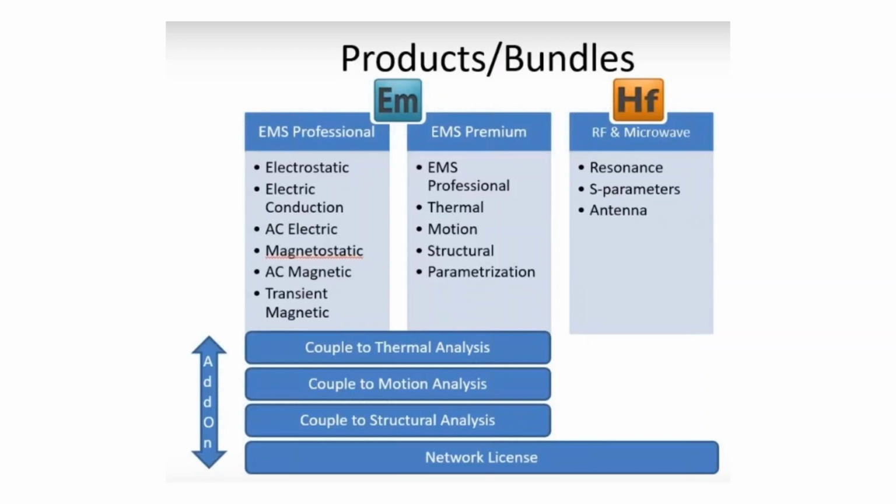Before I move to the next question, let me tell you that if you wanted to have an even more general simulation scenario where you would analyze, in addition to sinusoidal excitation at the voice coil, the effect of the induced voltage in the voice coil that comes from the motion itself, and how that impacts the overall behavior of the system, then yes, you would have to use coupling to SolidWorks motion.